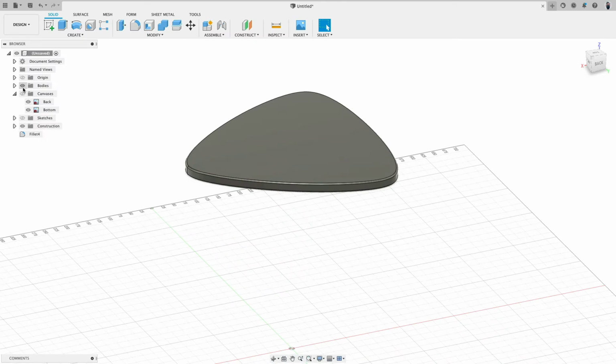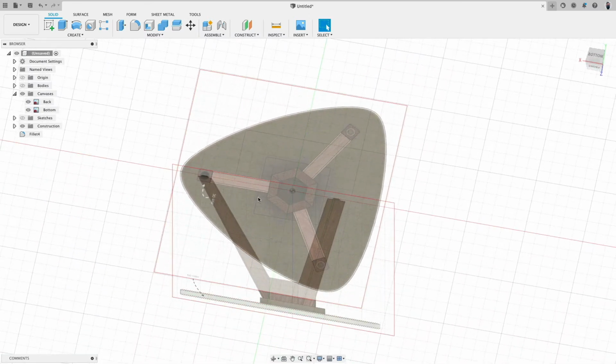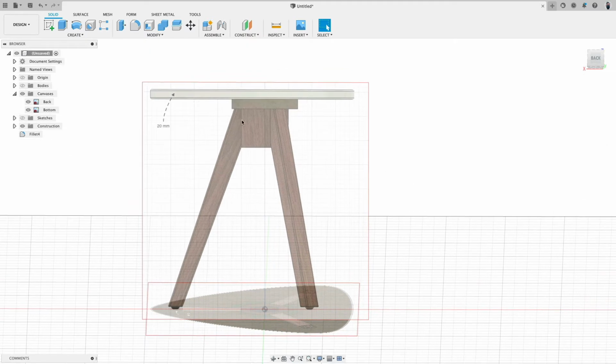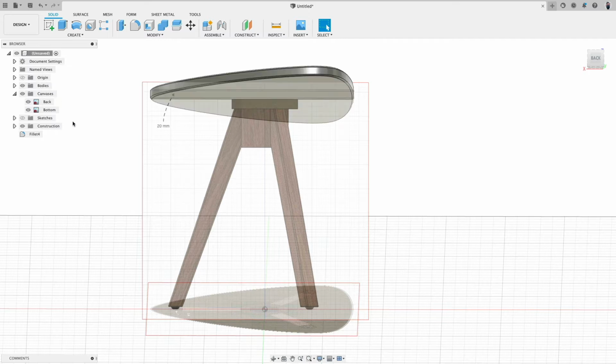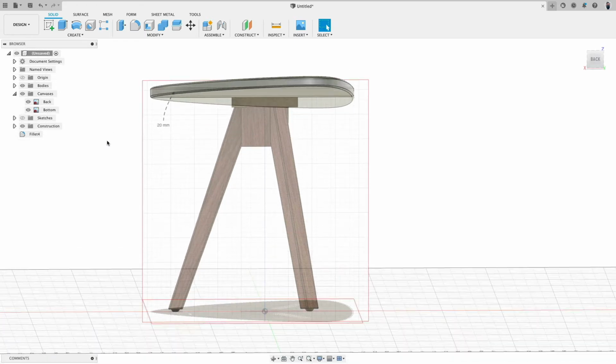The next piece we could model is actually this wooden base at the bottom. That is actually added simply to reinforce the material thickness. So when the leg elements are screwed or connected to the tabletop, we have plenty of material to make this a secure connection. So how can we do this quite easily? So we need a rectangular sketch, and the sketch has to be at the bottom part. So we will do it the following way.